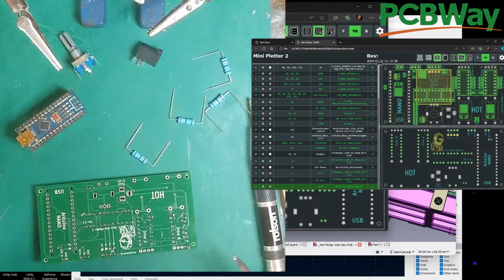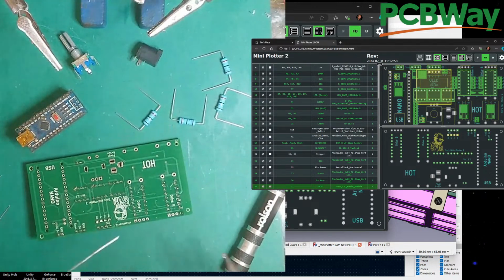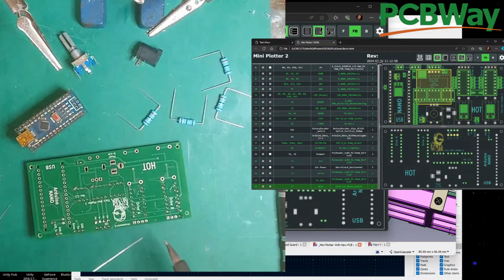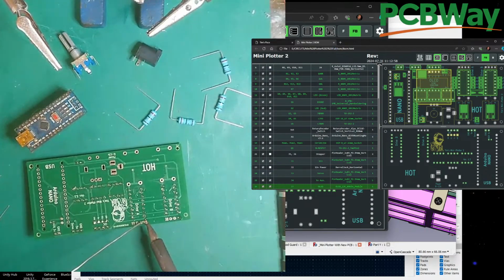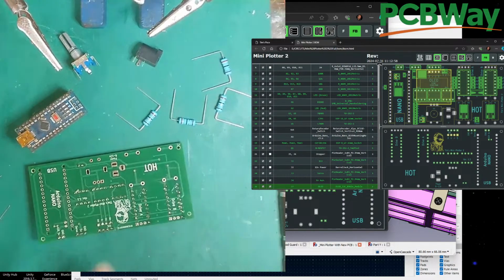When soldering headers, I don't know if people know, but what you'll find works best is to put most of your heat on the pin first to warm the pin up. Then once your pin's warmed up and flowing, start adding your solder to flow the hole. So let's see what they look like.